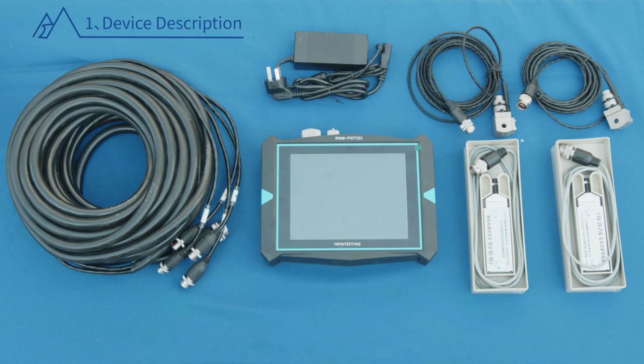3. Operation preparation. 1. Collect the pile soil information and geological exploration report. 2. According to the bearing capacity of the pile, choose a test hammer with an appropriate weight.